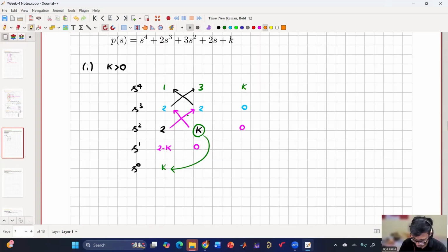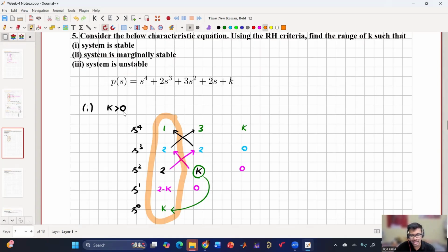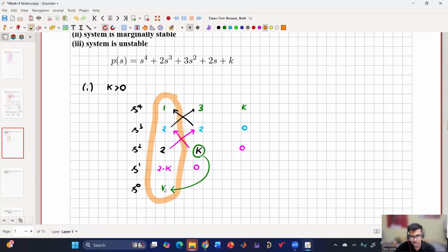So now if you see, whatever we have discussed in the necessary condition, that same necessary condition is also coming here, because the Routh Hurwitz criterion should say that it will be stable when K is greater than 0, right? That is also coming from this point. But it is not mandatory for us to do the Routh Hurwitz criterion if the necessary condition is not met. That is just to avoid the Routh Hurwitz criterion in at least some of the cases where we need not even go there. So in this case, if K is negative, we can directly say that it has roots in the RHP, unstable. But if they ask how many, then we have to do the Routh Hurwitz.